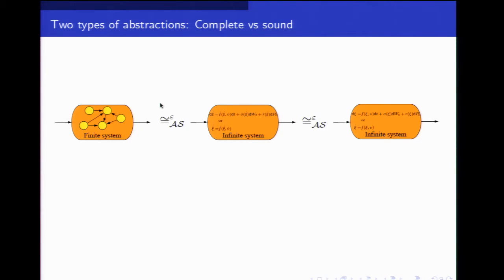Yes. I haven't elaborated under which condition I can provide the complete abstraction. If you can compute the complete abstraction, then you have this if and only if result. But your question is under which condition, under which dynamics, I can actually provide this abstraction. Yeah, I can elaborate on that. I will go and explain under which condition. So, if you have a linear system and it's controllable for this type of specification, actually there is an algorithm that you can use to construct the finite system that is exactly equivalent to the original differential equation.